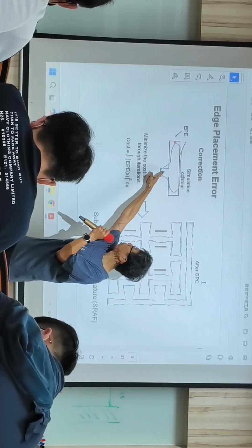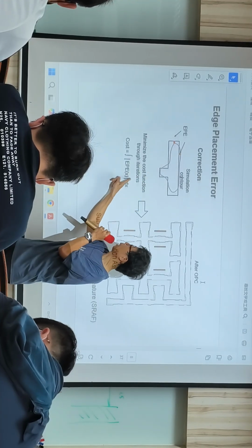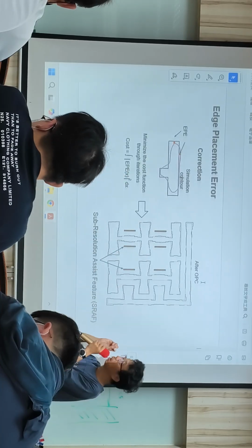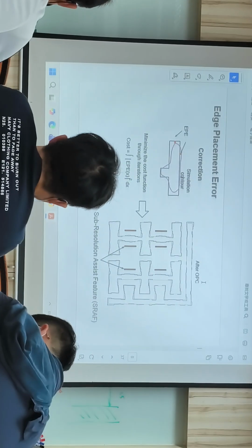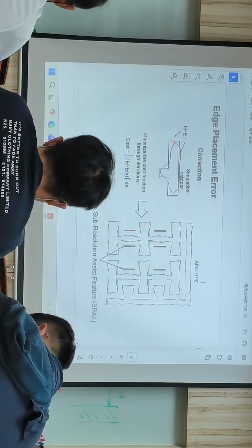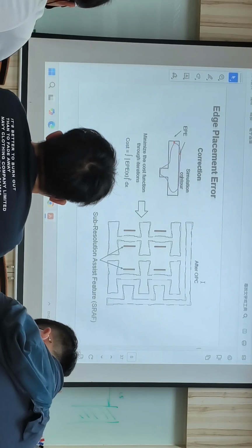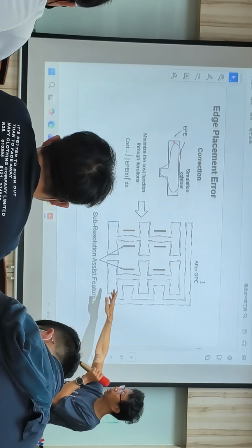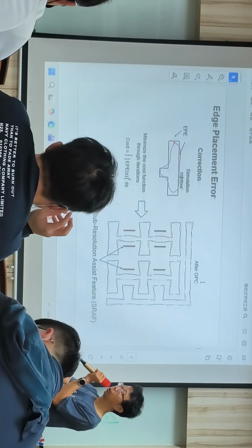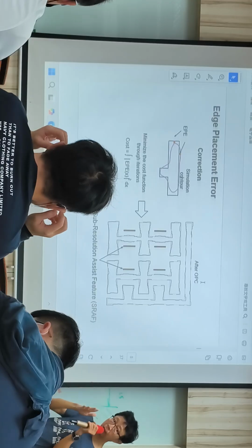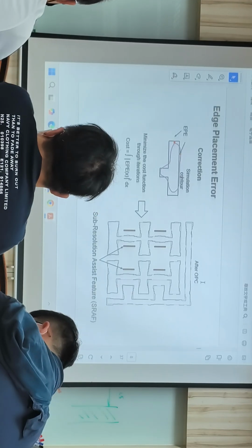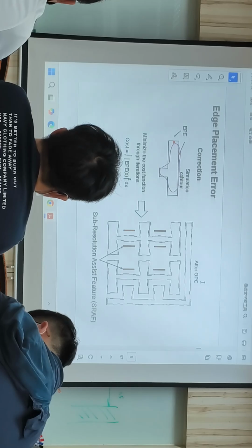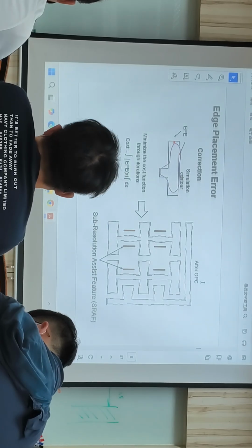Cost function plus or minus got squared, so it's all positive. And so cost function, the ideal is 0, but usually it will not. And when we do the OPC, basically we try to minimize the cost function. So we compare two OPC results, and at the end we can say OPC 1 is better than the other because it has a lower cost function.